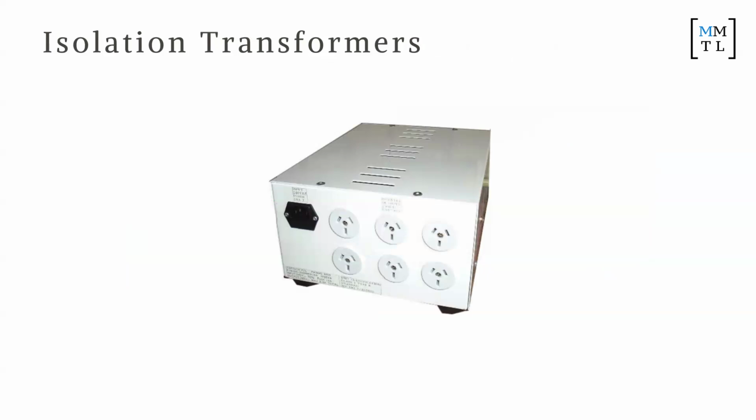Now, this is a tool that I didn't realize existed, but I learned about when I was doing startups, which is an isolation transformer. This isolates the power of your device from the electrical grid, and it actually guarantees electrical safety. So it's a very, very powerful tool if you ever decide to go into medical devices.